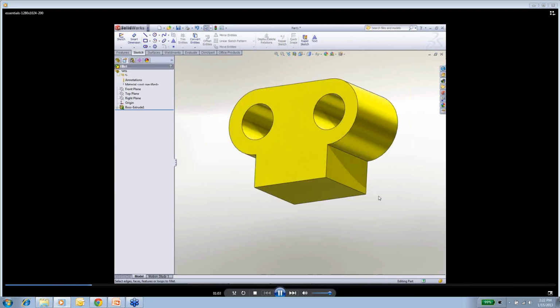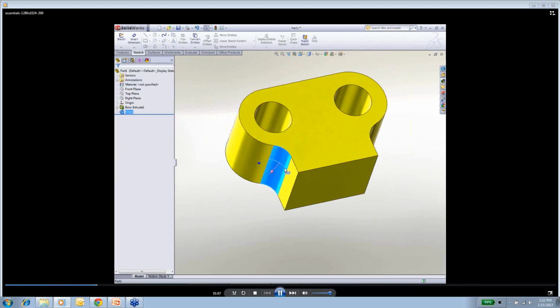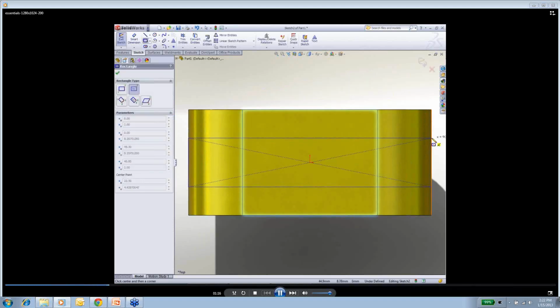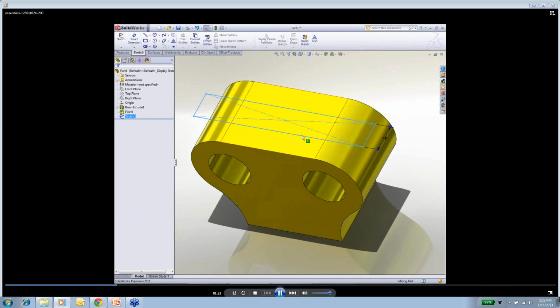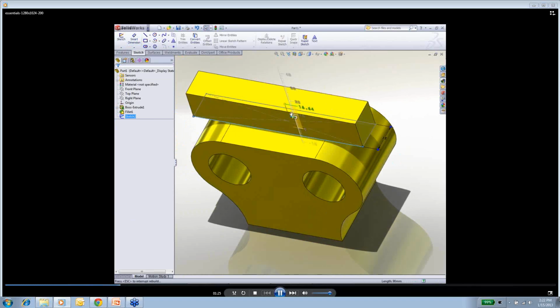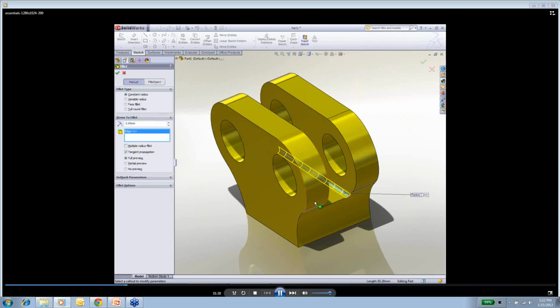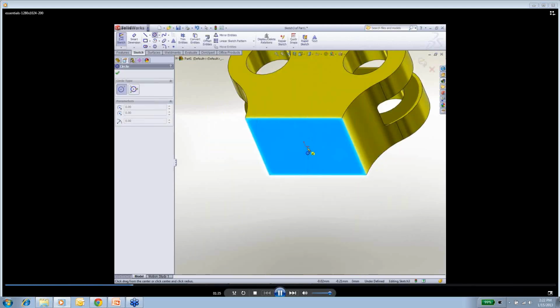There's a lot of ways to add depth. This is just extruding geometry directly. I also have these pick and place features, like here I'm adding some fillets. I can just say, put some fillets on this area right here, or put some holes in this area here. Now what I'm going to do is sketch a slot in this clevis, and I'm going to use a cut feature. Actually, what I can do is just pull the geometry. You see, if I go up, it's going to add geometry. If I pull it through, it's going to actually create a cut for me. Again, I add some fillets.